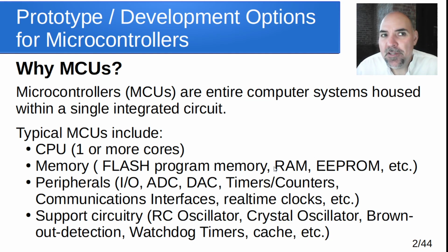There are usually several kinds of communication interfaces, SPI and I2C to talk to other components or other devices, and USB a lot of times. Other ones will have a UART to talk over a serial communication link to other things. And some microcontrollers even have wireless capability built into them, as far as the wireless chipset that allows you to talk to that.